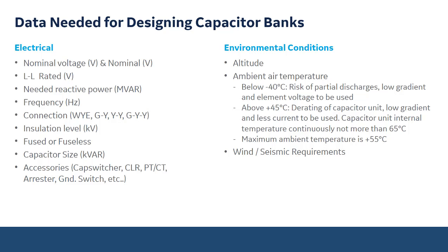The capacitor unit internal temperature continuously not more than 65 C, and we have your maximum ambient temperature is 55 C.